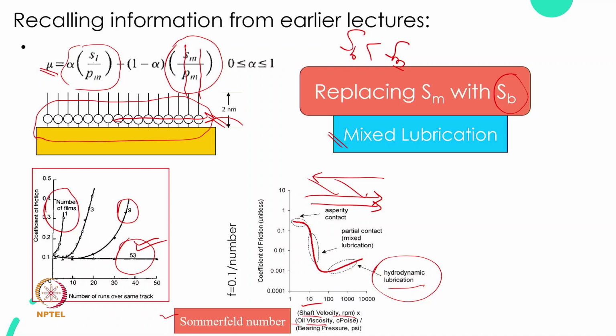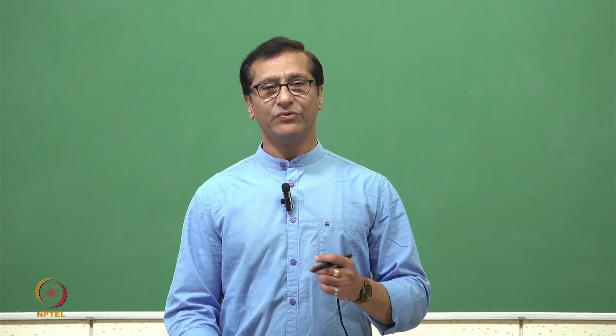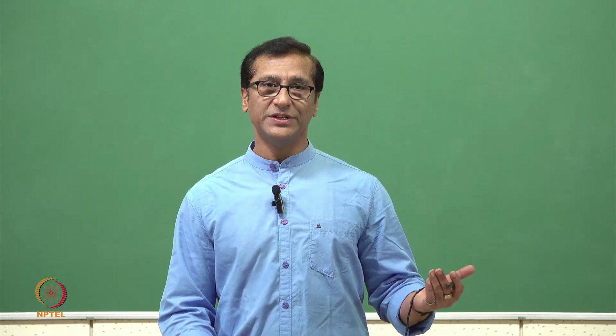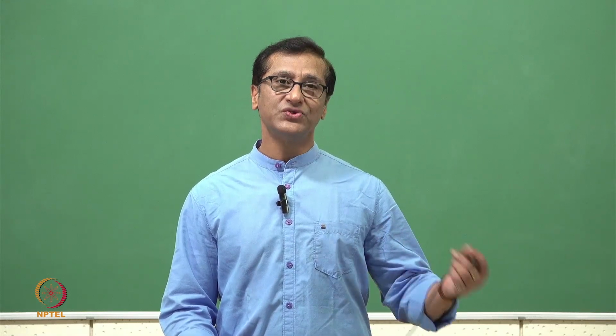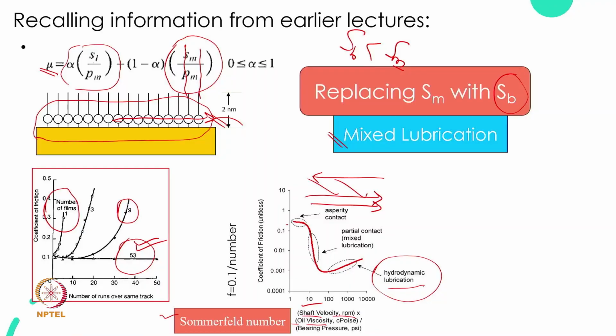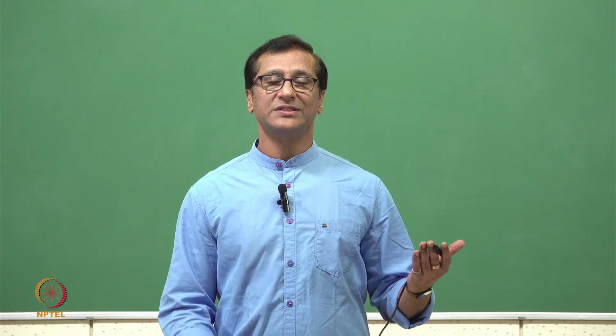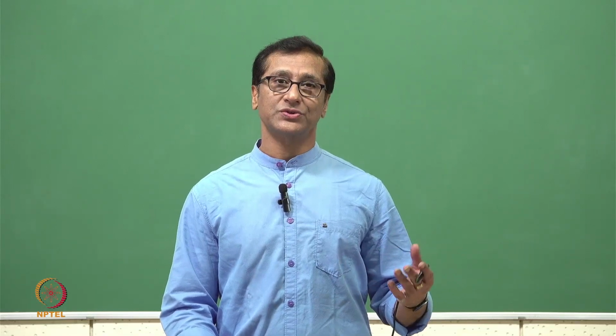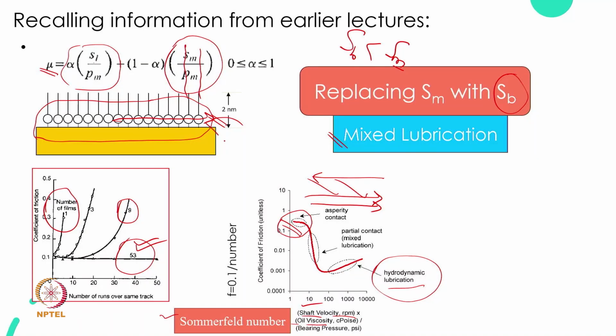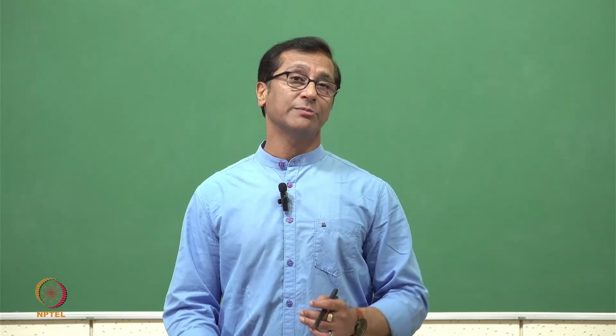Again, whenever there is a shaft and there is a bearing, the shaft will not immediately have 6000 rpm speed. Naturally, it will always start from 0. And in that situation, the shaft and bearing arrangement, or even the hydrodynamic lubrication mechanism, needs to go through this context. That means there is an initial contact, and then maybe after a few rotations, the shaft is levitated and the separation happens. For that purpose, we say the boundary lubricant layer or boundary additives must be mixed with a lubricant which will be required for hydrodynamic lubrication.